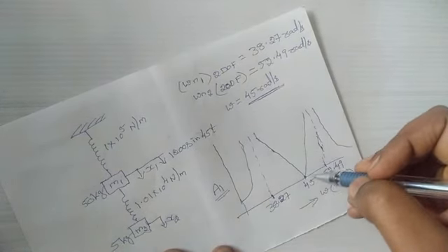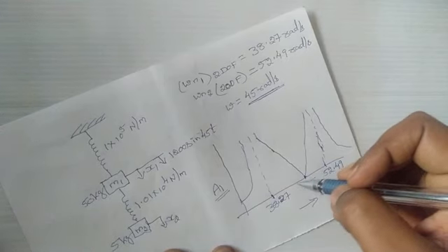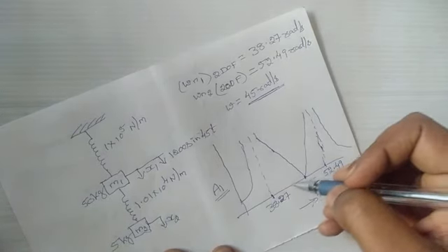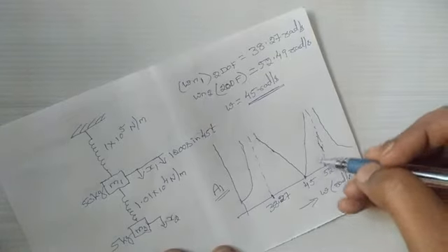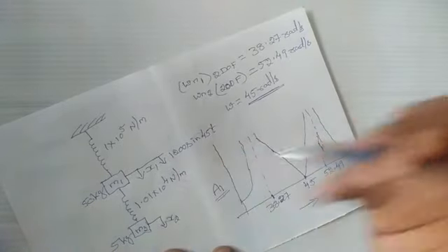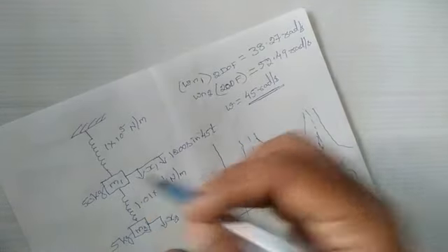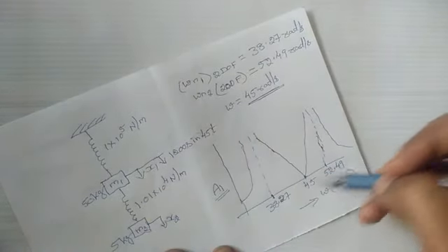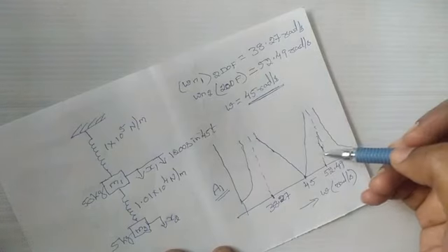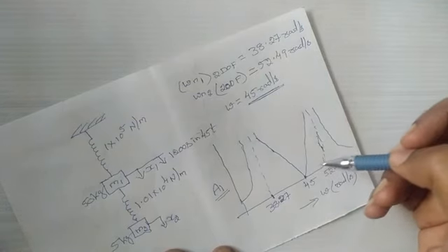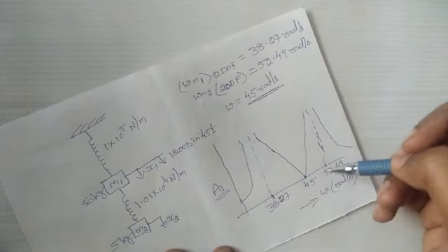So a little over this side you can go, a little over this side you can go, but more than that, if you vary the forced frequency, you're going to increase the amplitude of the machine. The absorber is not going to absorb the vibration of the machine for a wide range of frequencies. So this is what we need to understand from the concepts of the vibration absorber.